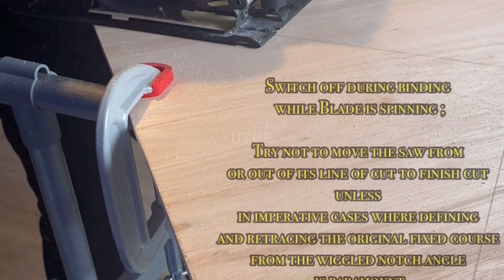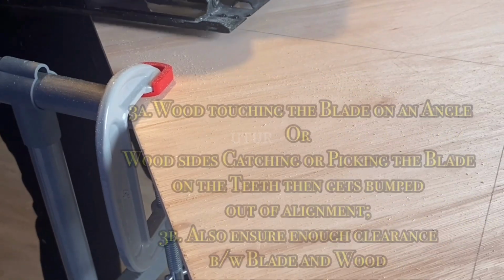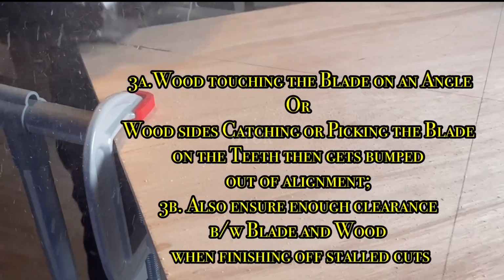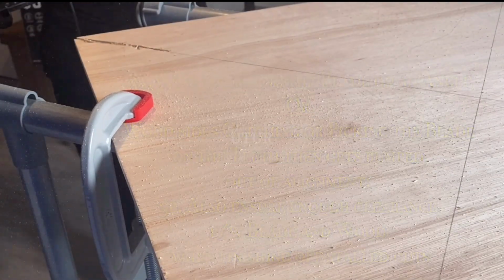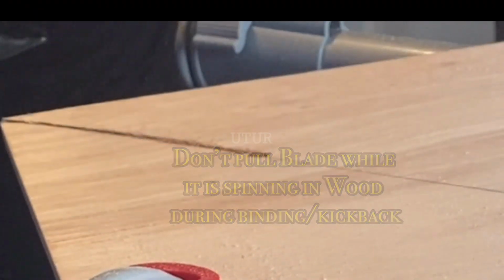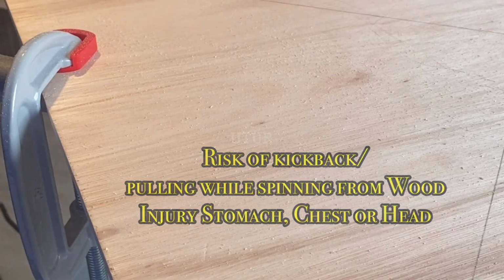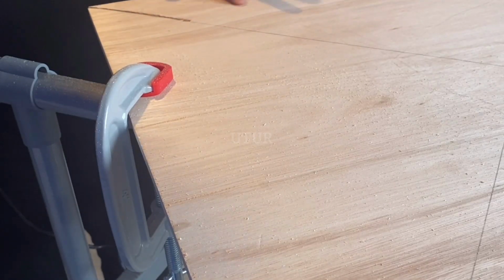The most probable root cause of why the saw blade has stalled or bound is that it has deviated from its line of cut or wavered during the cutting process. Suffice to say, cutting at an angle. Or it could be that the work tool was leaning on either side of the cut work pieces, where we were trying to make diagonal cuts, thereby causing binding.